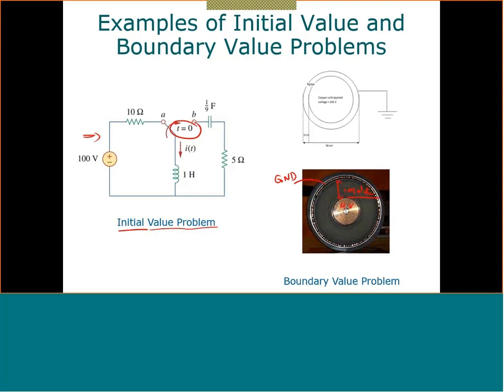So now, as a designer of the cable, you need to know what the voltage is at these points. Very important. Why? Because I need to know the electrical stress on my material, and to make sure that my material can withstand this high voltage. Now, I know the voltage at the boundaries only. I know the high voltage at this boundary, which is the high voltage of the cable, for example 100 kilovolt, and I know the voltage at the outside boundary, which is the ground. The voltage here is equal to 0. The voltage here is equal to x kilovolt. So I know the boundary.